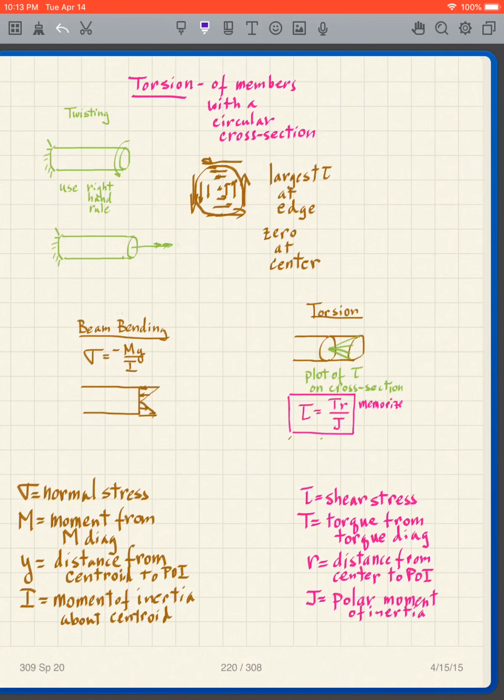And if you look at the way that the stick breaks in torsion, what you find is it's the outer fibers of the stick that begin to break, and then as you continue twisting, the fibers near the innermost begin to break. Then you keep twisting and twisting, but you're not able to break the stick completely. At the end, you have a very thin filament right in the center, and then you pull it and you can break the rest of it.